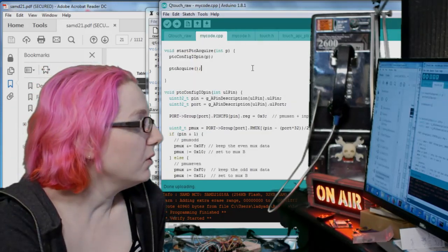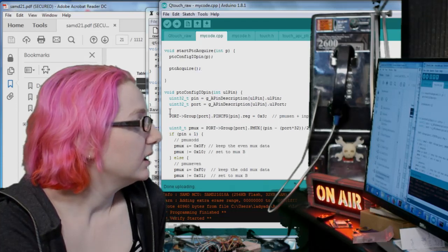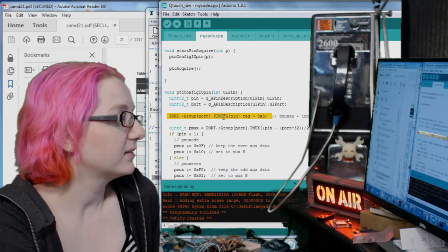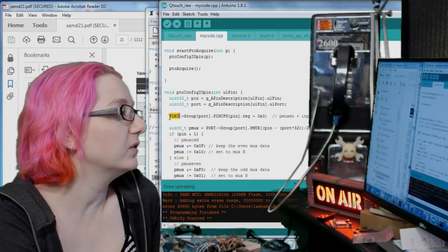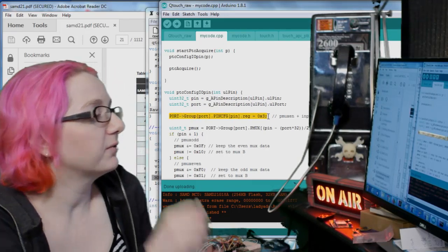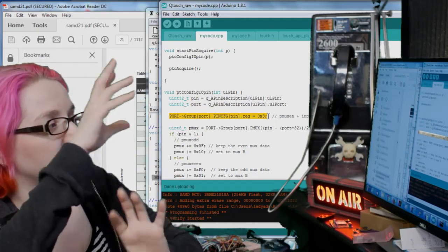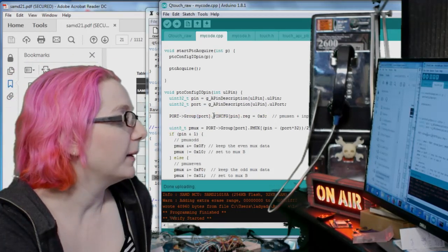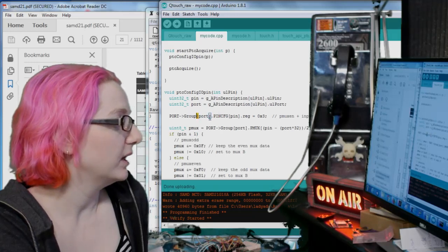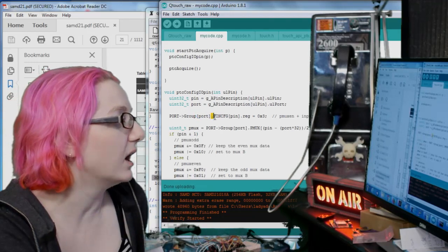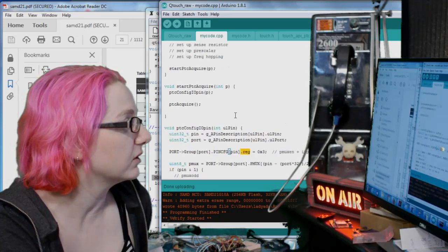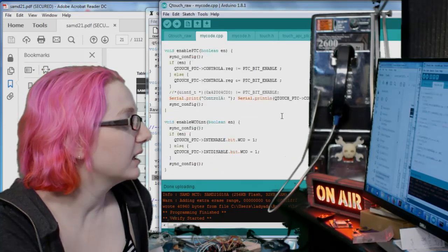So this is an example of some code that they use in ASF, for example, to set the pin configuration. Instead of figuring out the bit location and then shifting and ORing and ANDing, you can use union, indexing and union dots to get to the location you want and then set that register. And that's what I'm mimicking here.